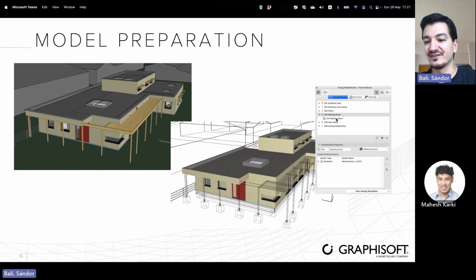If we have a very early phase and we say that we're designing a residential building, then maybe we just create one huge thermal block with all the residential zones in it, because let's say 95% of the building is going to be residential zones, and just a very small amount is going to be access areas and storage and something like that, which has slightly different requirements. So in this case, you can see that we have the thermal blocks, zones were collected into it, and we have building systems as well.